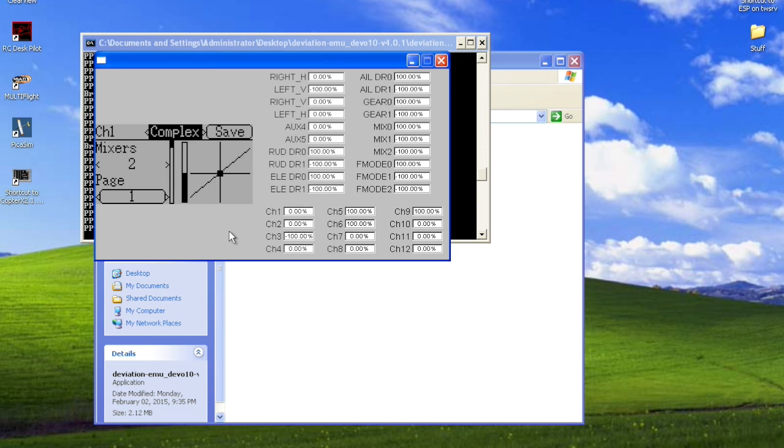You can toggle left and right and pick the rest of these pieces. Since I did enable it in heli mode, I have cyclic that I can adjust. I probably could have put it to plain and would have worked just fine. You just wouldn't have those cyclic options in this channel, but honestly, you can leave them unadjusted, as I've done, and it will work just fine.